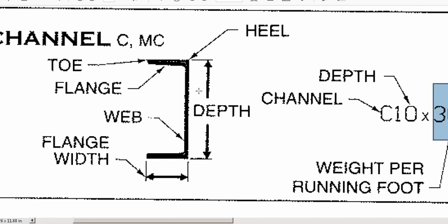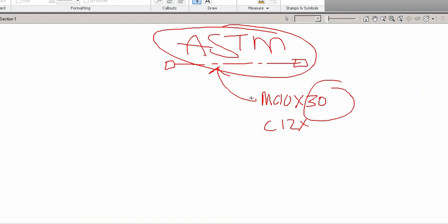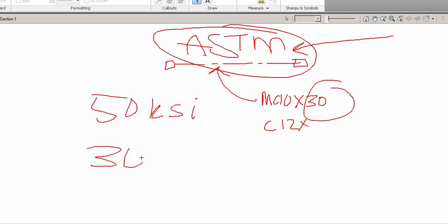Or we design with it, and if we get a bad beam, something can collapse. So it's really critical that when beams and structural steel are made, they're made to the ASTM standards. For example, one of the common values of steel strength that we have is 50 KSI. We also have 36 KSI, which stands for 36,000 PSI capability.